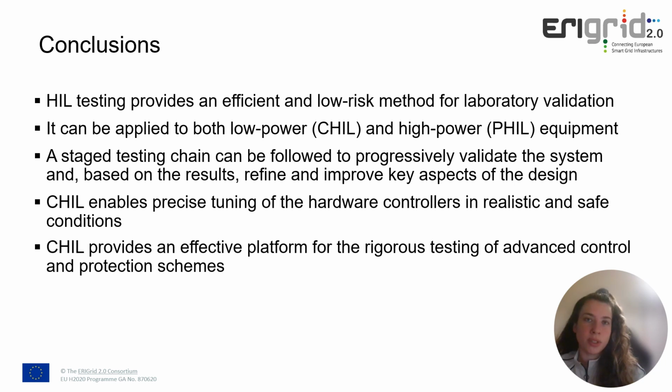Concluding today's presentation, hardware-in-the-loop testing provides an efficient and low-risk method for laboratory validation. It can be applied to both low power through control hardware-in-the-loop and high power equipment through power hardware-in-the-loop methods. A step-by-step testing chain can be followed to progressively validate the system, and based on the results, key aspects of the design can be refined and improved. Regarding control hardware-in-the-loop, it enables precise tuning of the hardware controllers in realistic and safe conditions, and provides an effective platform for the rigorous testing of advanced control and protection schemes.